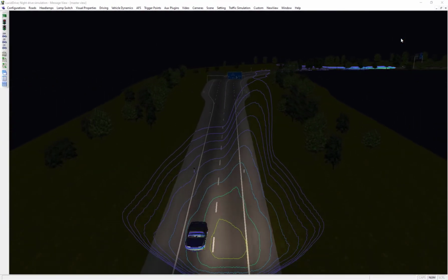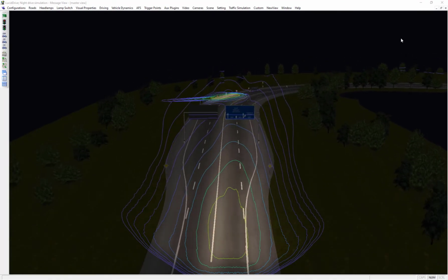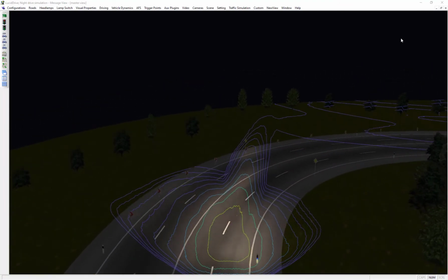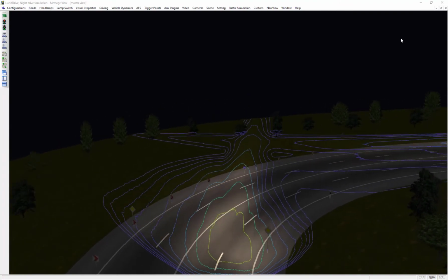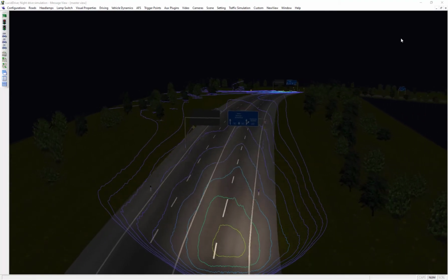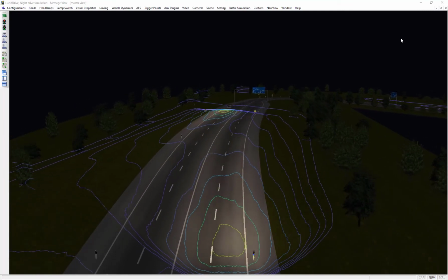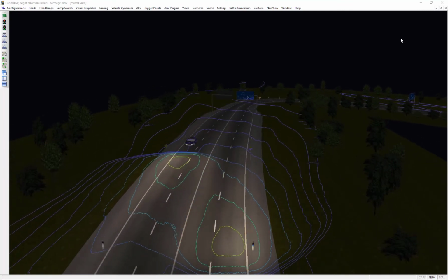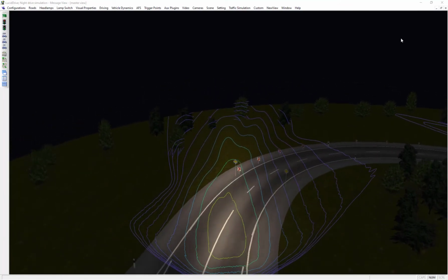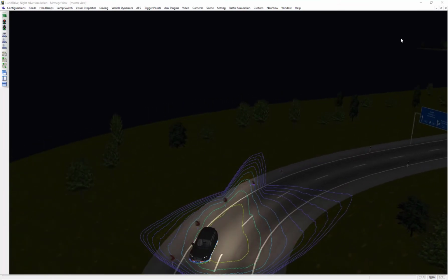In the first example, you learned how to add vehicles and determine the positions on the road. In this case, the added vehicles are on the same drive curve and have the same maximum speed, acceleration, and cornering speed. This means that all vehicles are driving one behind the other, and there is no overtaking. LucidDrive offers you the option to simulate a more realistic traffic situation. With the traffic simulation, you can assign speeds and accelerations to vehicles individually. The different speeds ensure that overtaking processes will take place at some points.